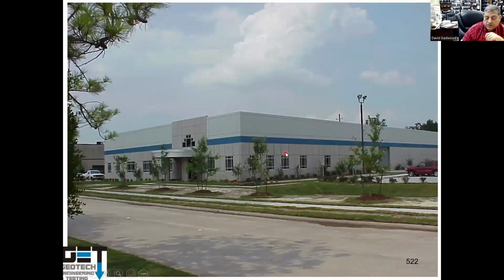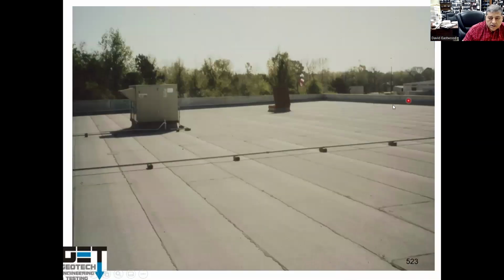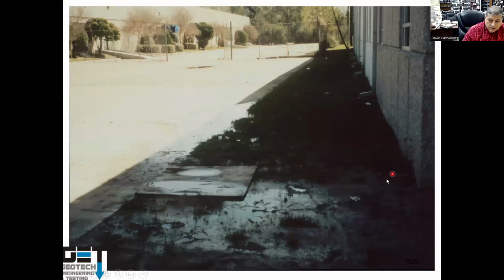Now, roof systems, sometimes they slope these roofs on these buildings. This roof is sloping. The building was moving, and they had gutters only on one side. This side of the building heaved up because all the water was dumped on one side of it. So the building was heaving up quite a bit because there were just gutters on one side.